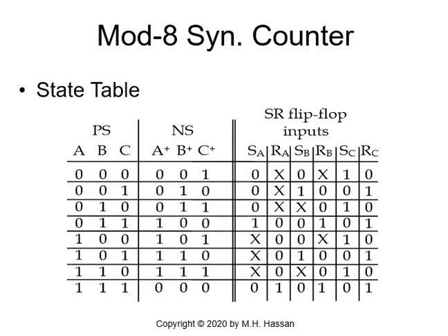Next, we will design a mod 8 synchronous counter using SR flip-flops. Since it is a mod 8 counter, we will have 3 flip-flops because 2 to the power 3 is 8. 8 states, or 8 counter, or divide by 8, all mean the same thing.